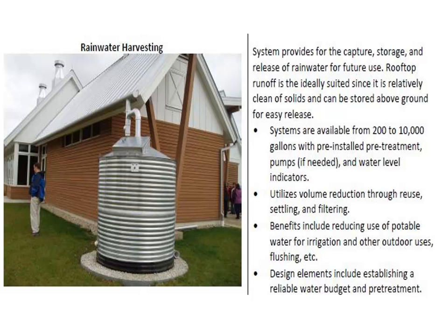How do you get the water through your hose? Like the hydrostatic pressure or just a pump? Good question. Because the tank's not pressurized, at my house I have it on a wooden deck and the garden is about 3 feet below that. And so it flows slowly through the hose. It's definitely not something you could have a water fight with, especially if you take the hose above chest level, then the water's not going to flow out of the hose at all. Yeah, so that's a really good issue. If you want to take it somewhere else, you're going to have to pressurize the tank or use a pump.